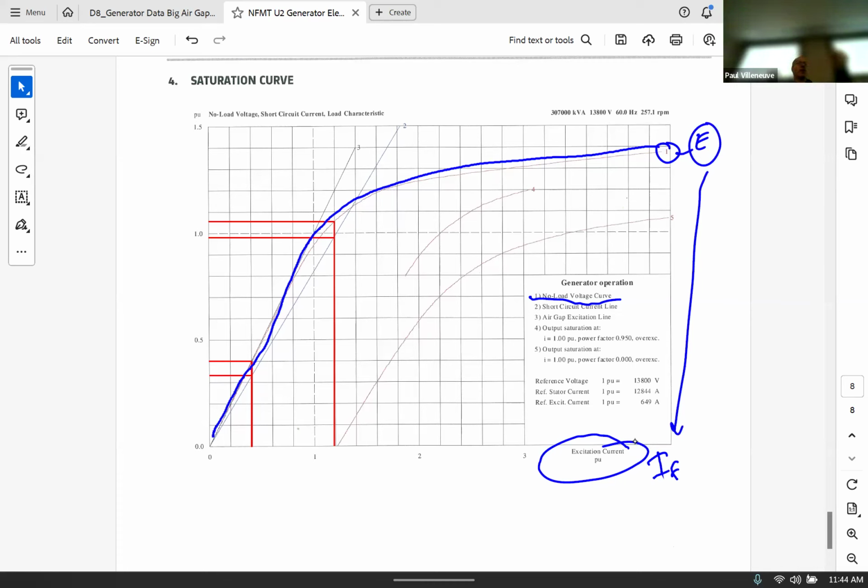You're literally driving that. And if you look at old school pictures of people working at synchronous generators, you'd literally see a person standing in front of a big resistor with a handle, and they would rotate the handle based on what was happening in the grid. So all these hydroelectric facilities, before they automated them, they literally had staff 24/7, and one of those people was responsible for turning the rheostat.